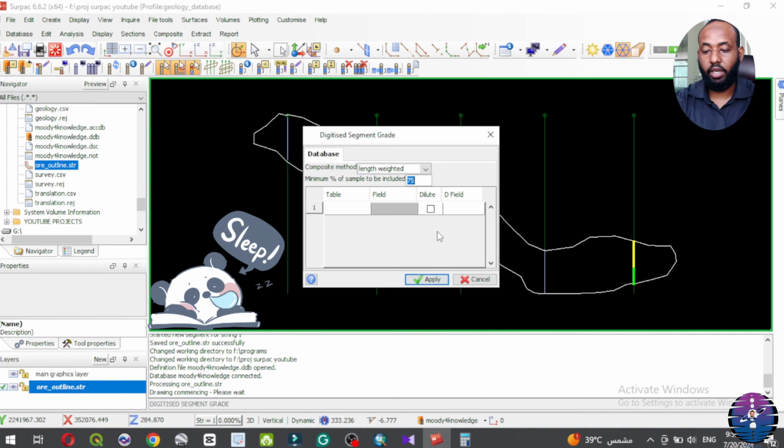For example, if the sample interval is 1.5 meters, obtaining the full 1.5 meters after drilling would mean we have 100% recovery. However, in most drilling operations, errors occur, which is a part of the process. So we need to account for an error percentage.